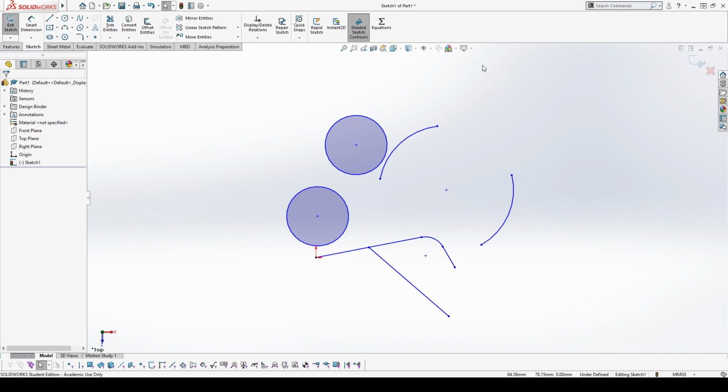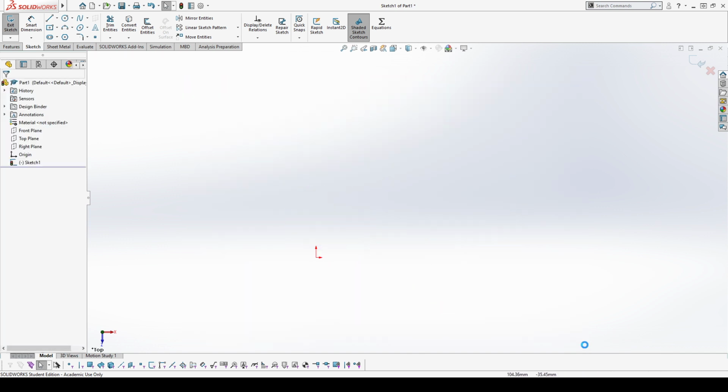So we have basic relations for lines themselves. They can be horizontal, vertical. You're basically doing line-to-line relations at that point with your origin, so your coordinate axes that are set up for you automatically. Then we have point-to-line relations. They can be coincident, so just lying along that line. It can also be a midpoint, like we were showing here. Arc-line, you've got tangent, you've got same, equal curve length, and then arc, you have your co-radial, concentric, equal curve length relations, and that kind of stuff. So that's everything for relations. Let's clear out our sketch and we can talk about some other dimensions.